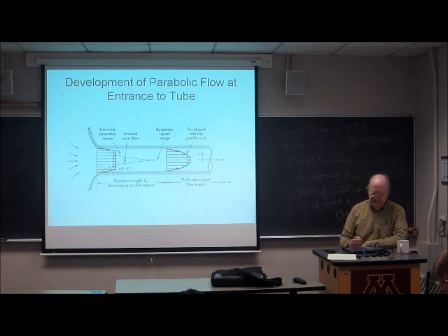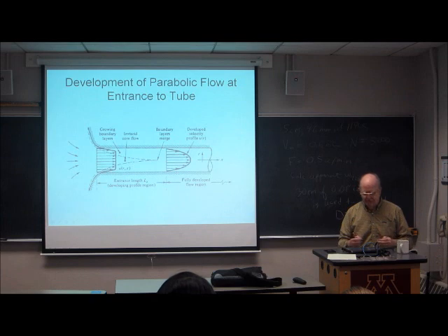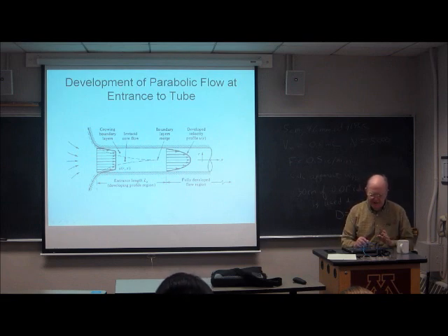The other thing I wanted to point out is we assumed the steady state solution, meaning things no longer vary as a function of time. Well, at the entrance to a tube, you're not immediately in steady state. It takes a while for the steady state to develop. And this is what we call the entrance length condition. So that at the very front end of the tube, the parabolic flow has not been fully developed yet, and it looks a lot flatter.